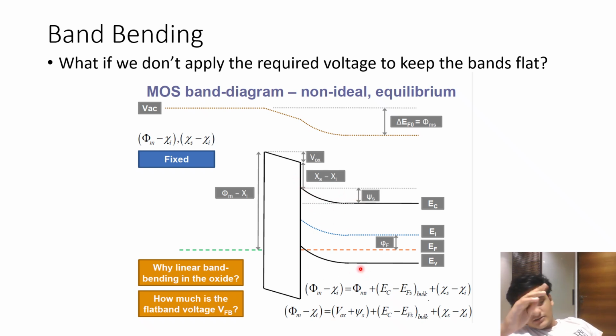And yeah, so that's essentially how the bands bend in order to keep the Fermi level flat, while also reconciling this difference of work functions, where this work function is smaller than this work function. And essentially that's what they're saying, that the difference in the individual Fermi levels when you had kept them apart from each other and the vacuum were at the same level is equal to the difference in the work functions of the two metals.